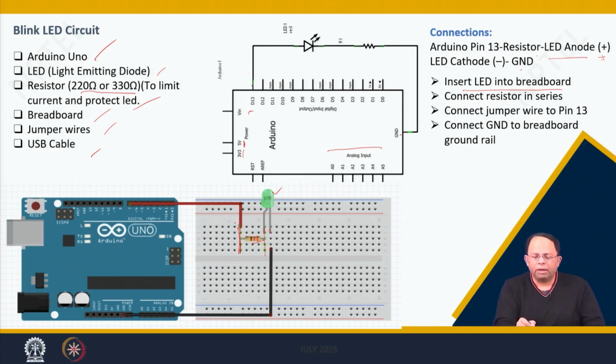Because it is connected, now I can put a jumper wire over here, and it goes and connects to a digital pin of Arduino. And from this side, I can directly take it and connect to this particular ground point, so that the circuit is connected, right? So here we are first coming over to here, and this is the ground, and then we connect this to the ground pin.